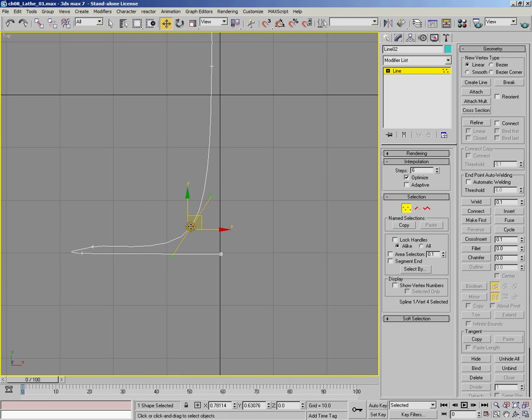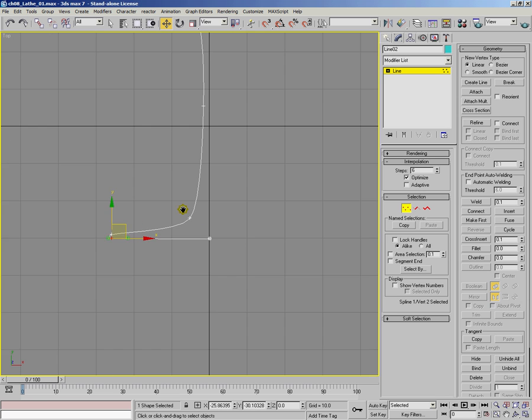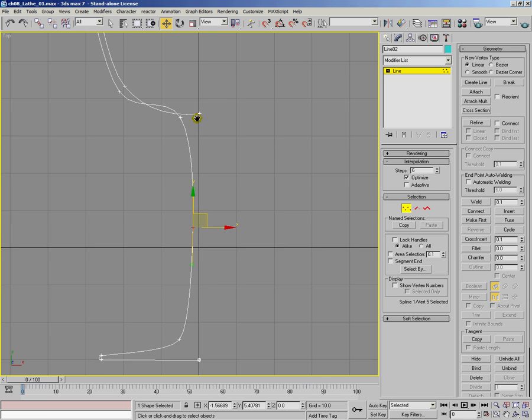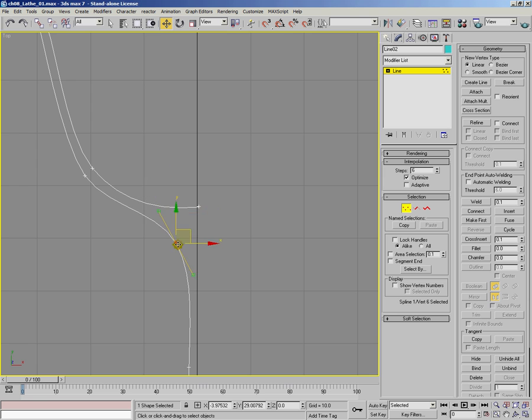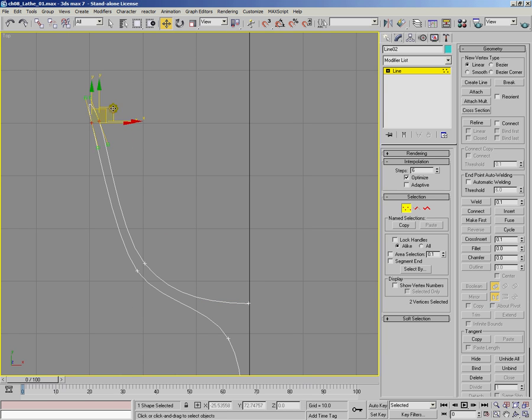And it's just a case of now editing this into a shape you think is a bit more attractive. Let's say we don't like this, so I'll just hold on Shift to break this. Stop getting this excessively large sort of curve here. So there we go. Just make this a bit more linear. We've got the base there. You can see this kind of needs to be pulled down here to make the inside of the glass kind of flat at that point. We'll just move this up here a little bit, in here like this.